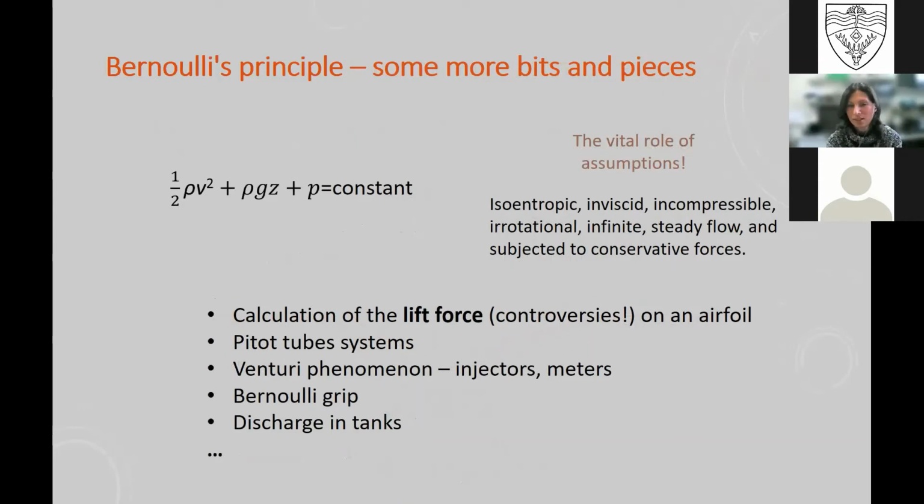And there are a couple more things. Not only the applications, but I find very interesting the role of the assumptions. It's something that in physics and engineering, people do quite a lot. So every time we go for solving a problem, we have to consider whether the flow fulfills certain criteria. In this case, we're talking about an isentropic, inviscid, that is non-viscous, incompressible, irrotational, infinite, steady flow that fulfills the equation, and also subjected to conservative forces. So again, this is an interesting way of looking at it too.